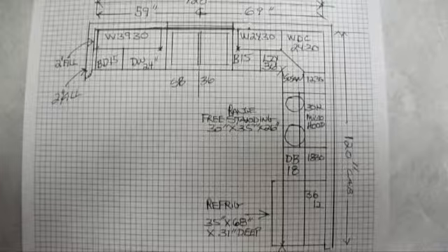So do the math. 59 inches less 39 inches less 18, which is half the window. That's a balance of 2 inches. So working from the 69 inches, you subtract the 49 inches we did for the wall cabinet. That leaves you 20 inches. 18 inches is the center point of the window, or half. That's a balance of 2 inches. Perfect 2-inch reveals on both sides of the window.